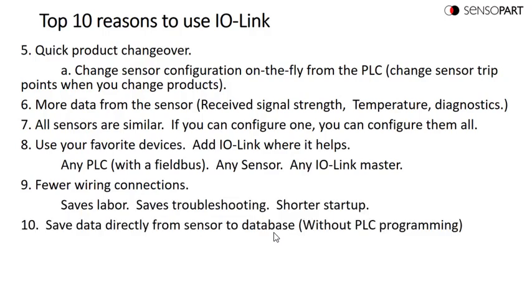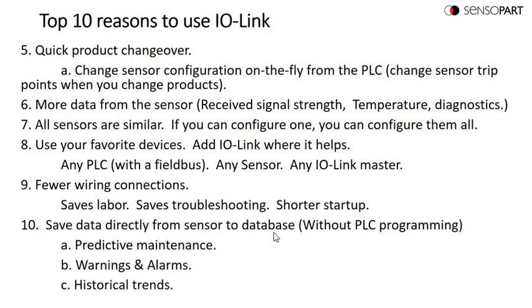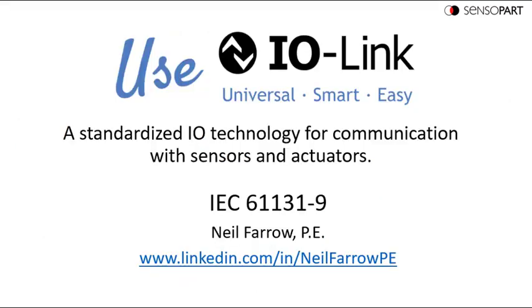The last thing, you can, with some IO-Link masters, save data directly from the sensor to a database. You can do some HMI screens, diagnostic screens, talking to the sensor without going to the PLC for things like predictive maintenance, additional warnings, historical trends, SPC, statistical process control. Next, we'll show an example of loading an IODD file with a web browser.